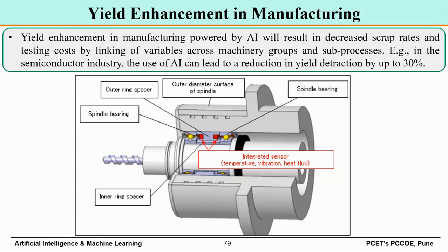So what you can do as an engineer, or what will be the feature extraction, you may be interested to know what is the life of the bearing, or you want to predict whether the bearing is working or failed. Right? The bearing is inside, not visible from outside. So how will you find out whether that bearing is working or not? Noise, one of the features. So noise is one feature. Based on that we can predict if there is a failure of that bearing.